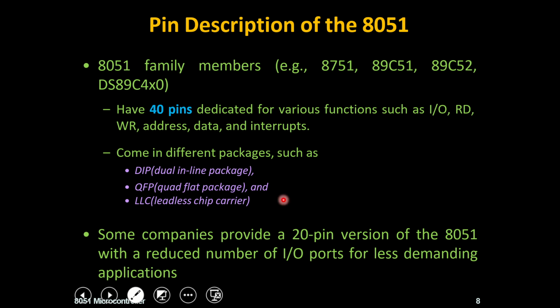The 8051 comes in different packages: dual inline package, quad flat package and leadless chip carrier package. And some companies provide a 20 pin version of the 8051 with a reduced number of input outputs. So it depends on the application.